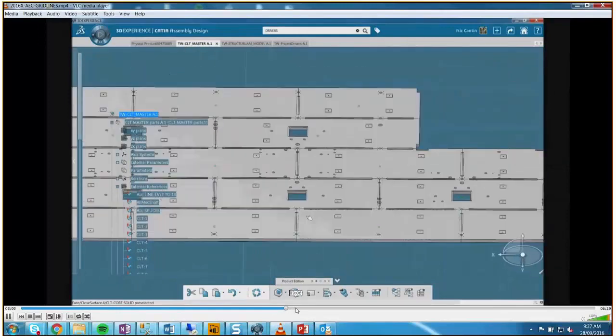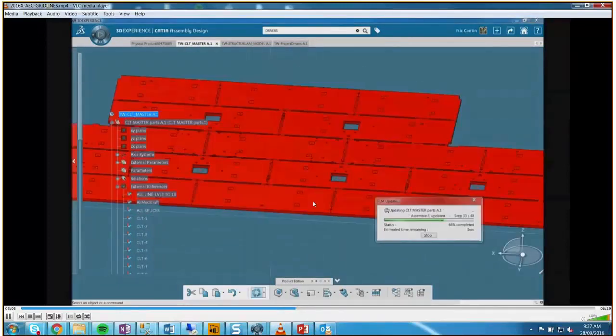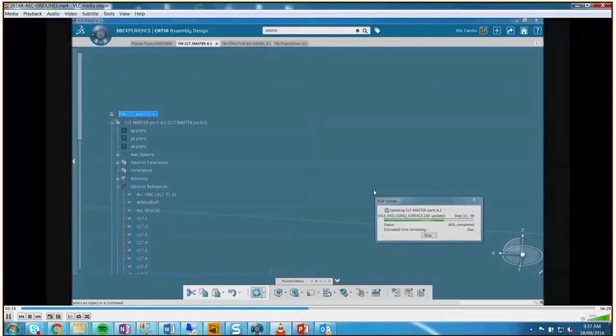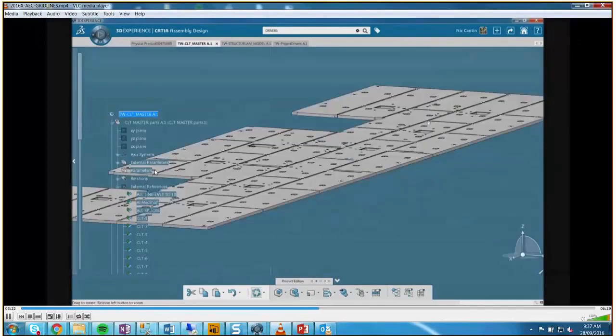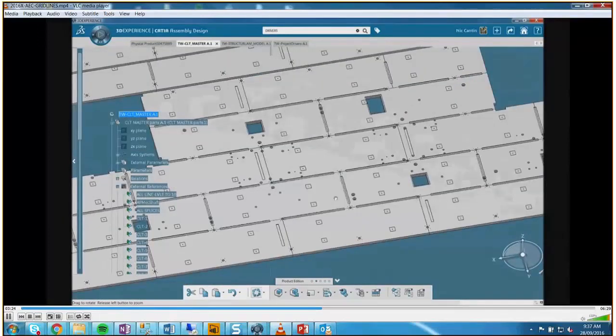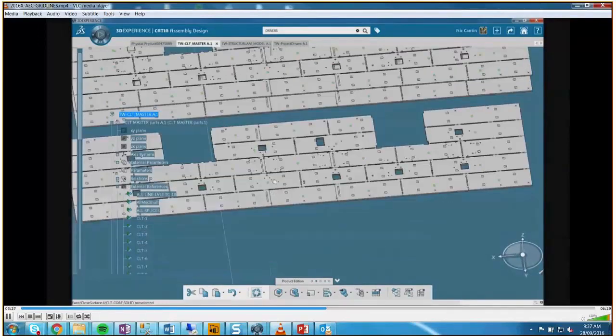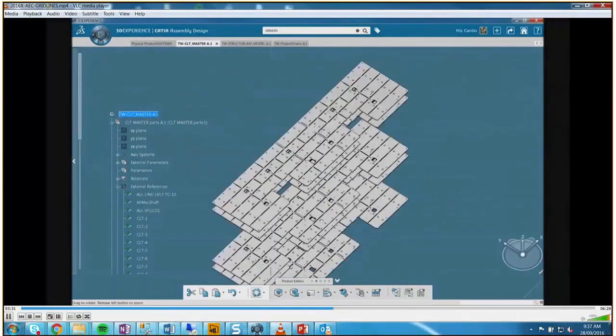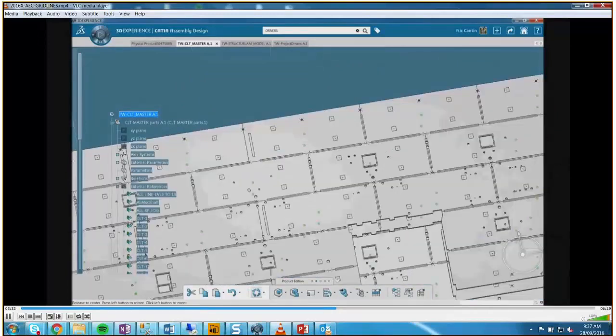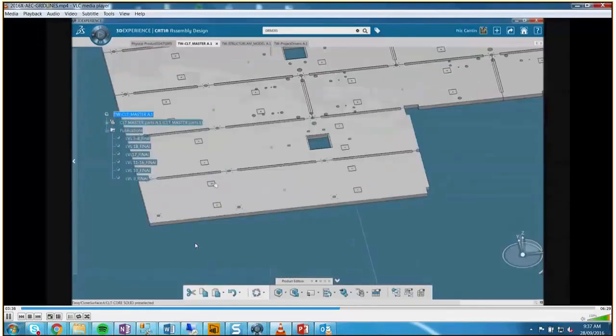So now we've made a few modifications to the drivers. We've shifted a grid line, moved one of the penetrations for the HVAC mechanical assembly, and now we're updating the master level. Essentially, each panel has the same outline and profile, so we're able to update level 3, and levels 9, 10, and 18 would update as well, just for the profile.